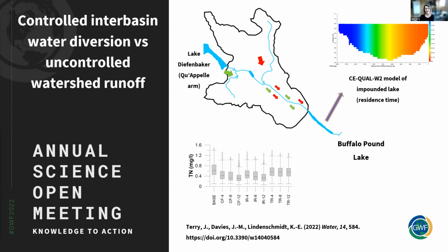So basically, just quickly going back. I have been modeling the impact of longer term water transfers from Lake Diefenbaker, because as I was trying to say, the Water Security Agency cannot just release lots of additional water straight down the Upper Qu'Appelle River channel into Buffalo Pound to flush the water, because it's a very shallow system with a maximum channel capacity, and they have to be very careful not to flood the area. And so really it is a question of optimal timing, of how and when best to release the water transfers of this considerably better water quality to help flush the lake. So that is what I have been modeling.